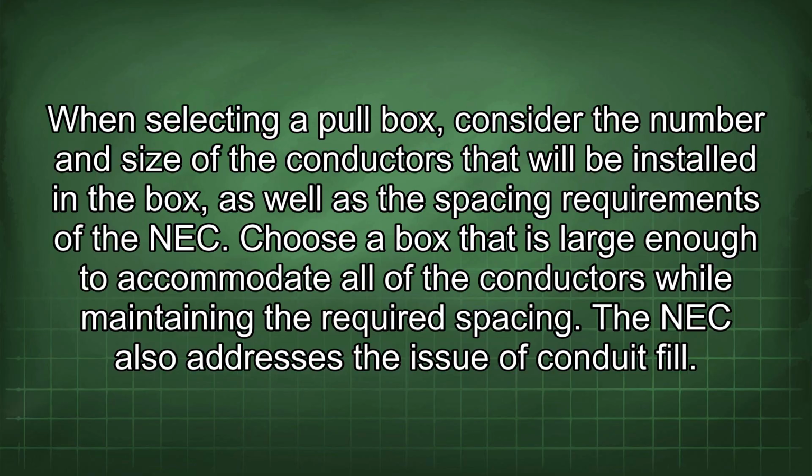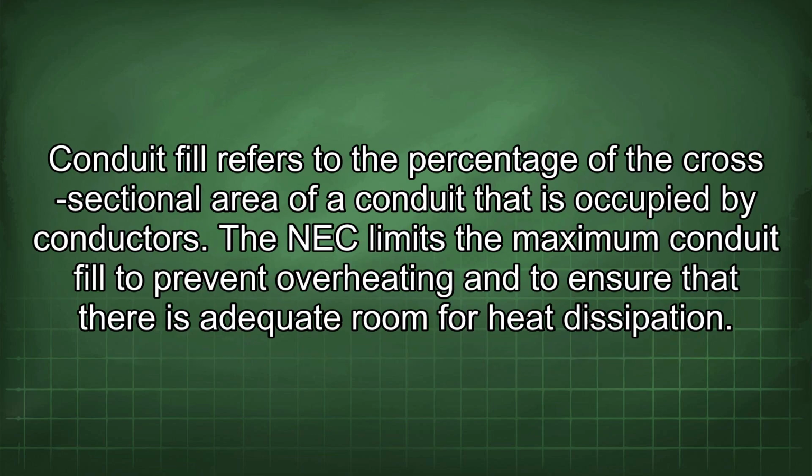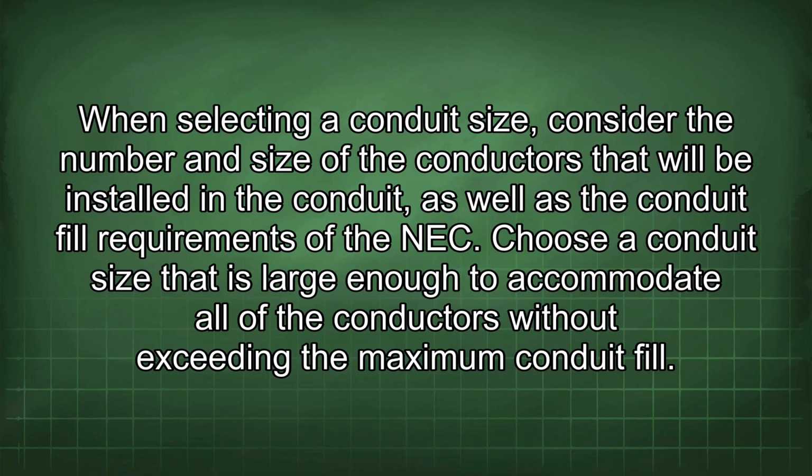The NEC also addresses the issue of conduit fill. Conduit fill refers to the percentage of the cross-sectional area of a conduit that is occupied by conductors. The NEC limits the maximum conduit fill to prevent overheating and to ensure that there is adequate room for heat dissipation. When selecting a conduit size, consider the number and size of the conductors that will be installed in the conduit, as well as the conduit fill requirements of the NEC. Choose a conduit size that is large enough to accommodate all of the conductors without exceeding the maximum conduit fill.